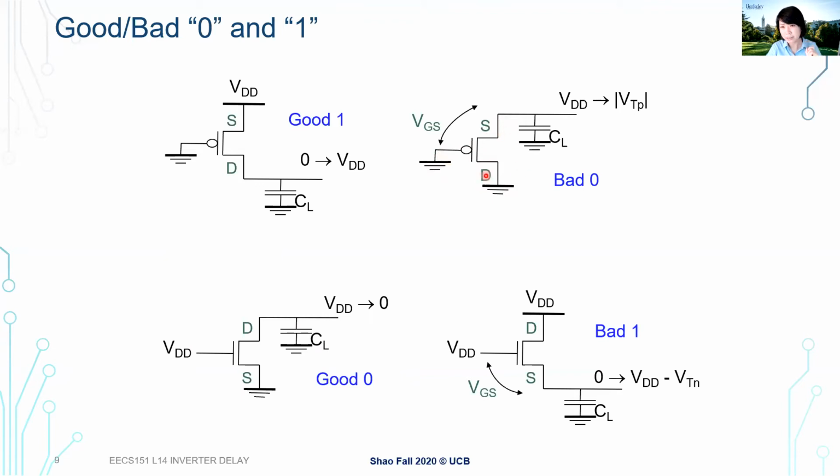But even though the gate is on, my output voltage is basically my source voltage here, this node. Remember, whether my transistor is on or off depends on the gate to source voltage, which needs to be not 0. Remember the line where we drew the bottom line: the transistor is on when the gate to source voltage is greater than the threshold voltage. The same here, this is our gate.